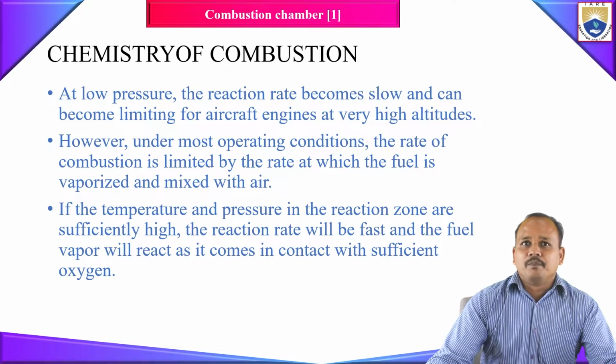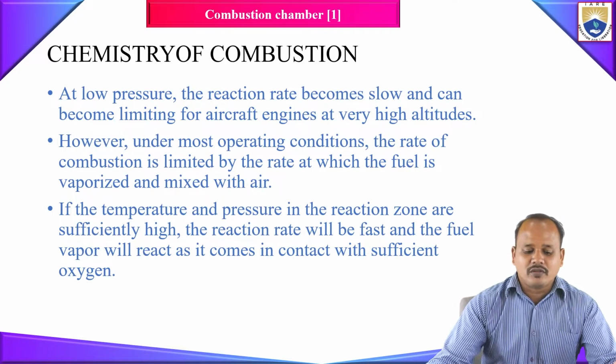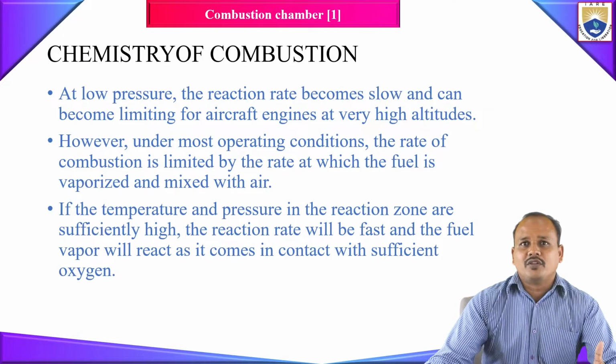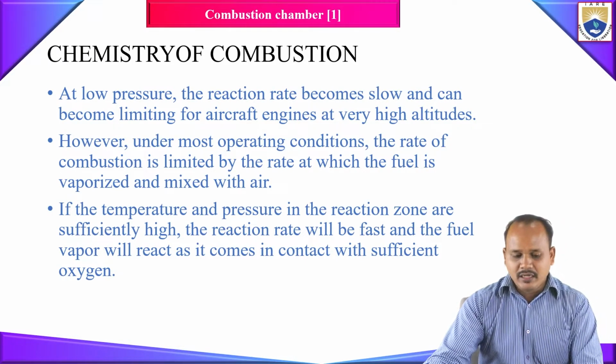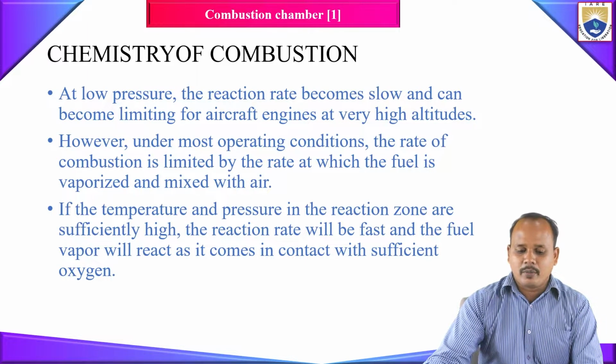If the temperature and pressure of your combustion zone or reaction zone are sufficiently high, the reaction rate will be faster, and the fuel which is being evaporated will easily come in contact with your oxygen. Obviously, you need oxygen for the combustion process. So when it comes in contact with oxygen, you will have easier, proper combustion.